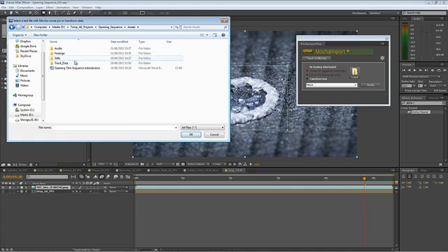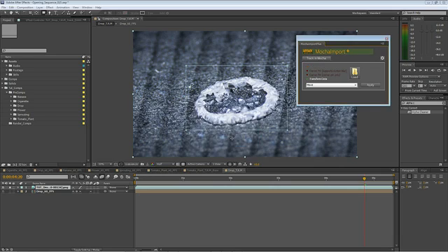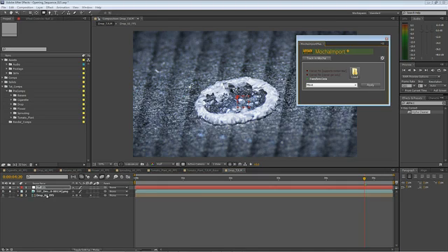In here I've got the track data folder, and here's the file I just saved. Hit OK, and Mocha Import Plus is asking me which clip did you track. Well, I've tracked the .comp time remap track. OK. Make sure I'm not selecting anything and hit apply. That would create a null called Mocha Move Null.